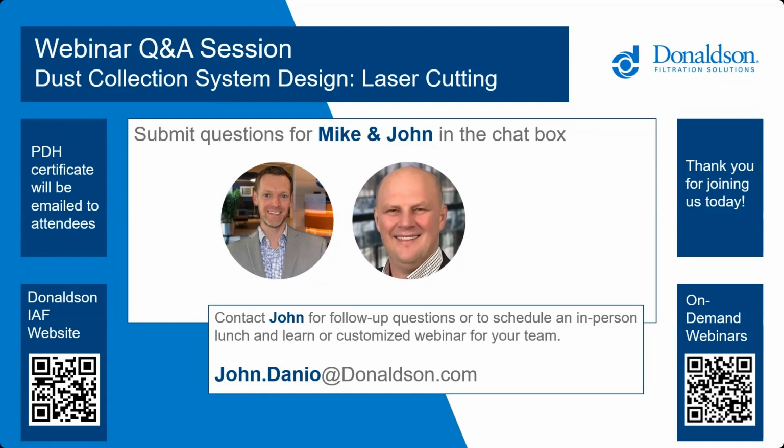So the next question, I'm not really sure exactly which system they're talking about, but what types of challenges has the implementation of this system had? So maybe a couple of common challenges you run into, Mike, when it comes to laser cutting systems. Yeah, I would say the biggest thing is just doing your homework ahead of time. So making sure you have enough airflow through your ductwork, making sure you have enough filter media to handle the dust and fume and particulate that the laser will be generating.